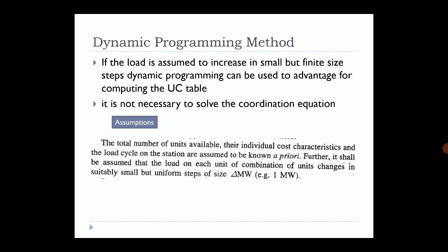It tells you the unit commitment chart: that if this is the load, this generator should be turned off, this should be turned on, this should be turned off, this should be turned on. So you can have a chart and the operator can see. He need not do the calculation. The calculation is what you are doing for the operator, and you are making a chart. So you are the supervisor of any kind of generating station, and you are providing this chart to the operators. And it is not necessary to solve the coordination equation. So remember, what is the coordination equation? The lambda equation. So that equation we need not solve here.